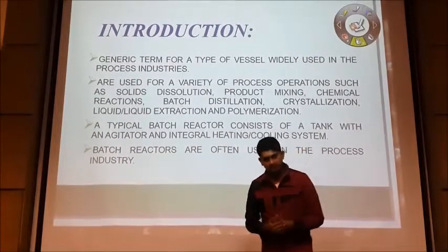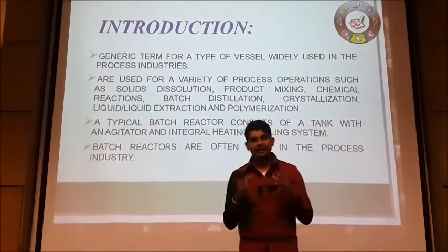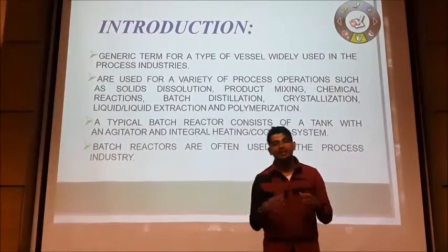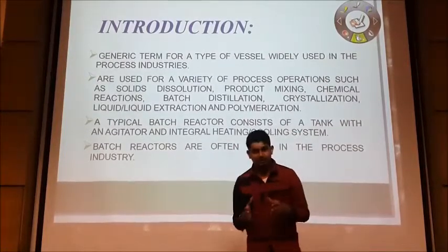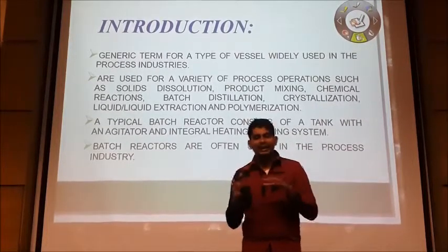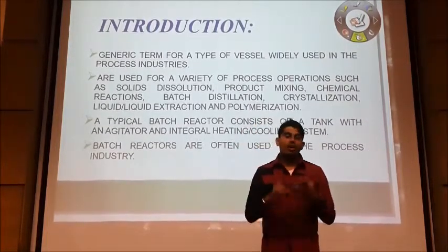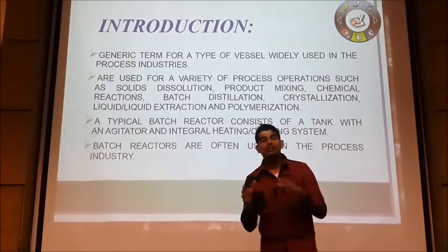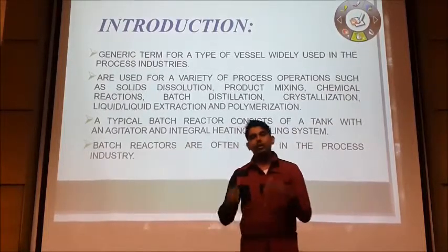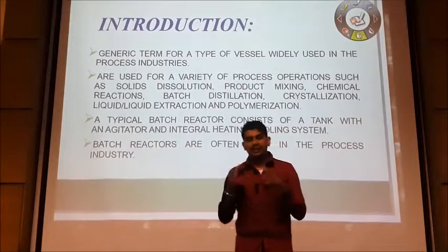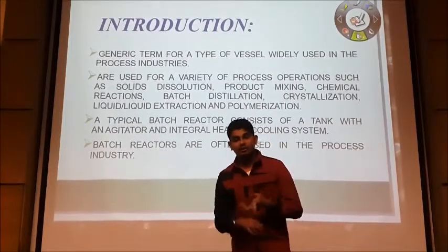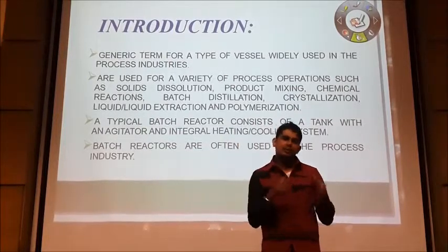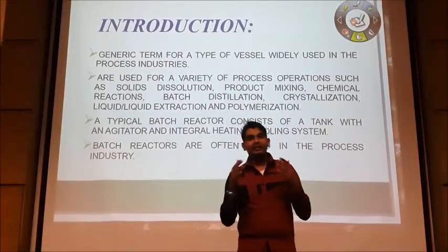So what is an agitator? An agitator is an impeller blade that is mounted on a shaft. A wide range of blades are used, and the blade covers about 2/3 of the diameter of the reactor. Where viscous products are handled, anchor-shaped paddles are used, which have a close clearance between the blade and the vessel walls.